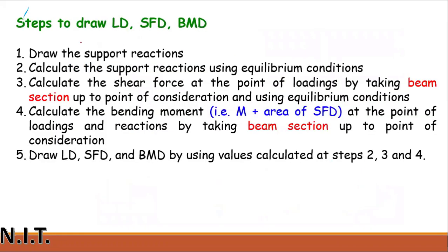There are a few steps to draw the load diagram, shear force diagram, and bending moment diagram. The first step is to draw the support reactions. First of all, you need to draw the reactions, then calculate the support reactions using equilibrium conditions, and then find the values of those reactions.